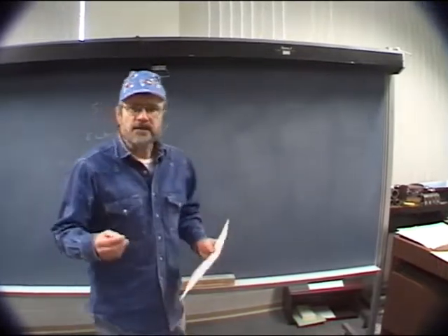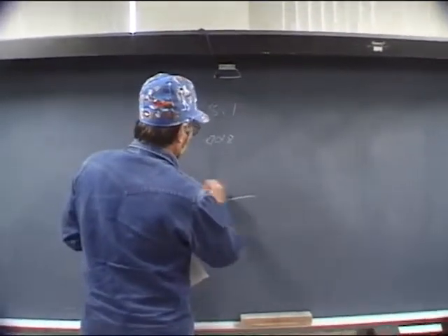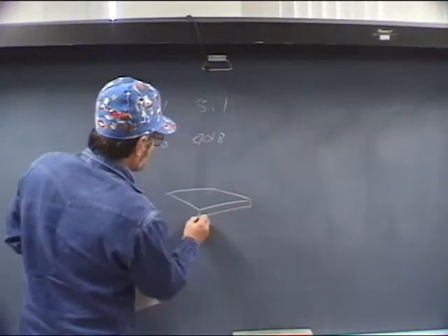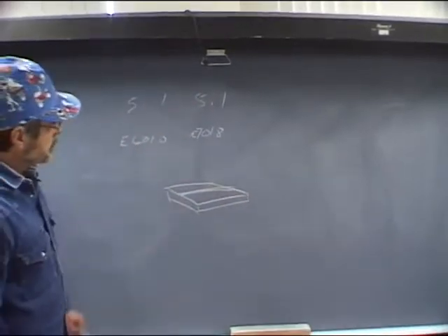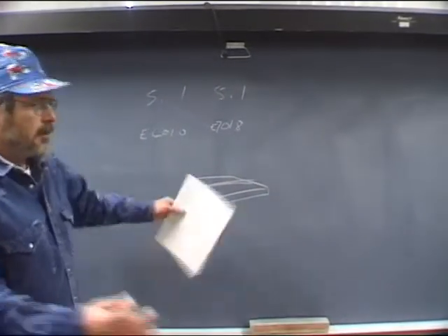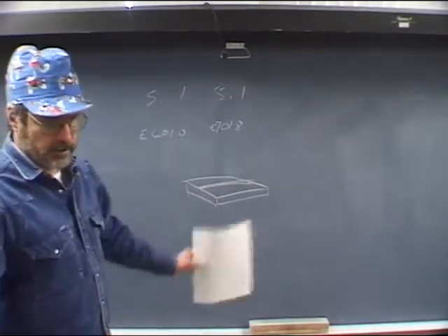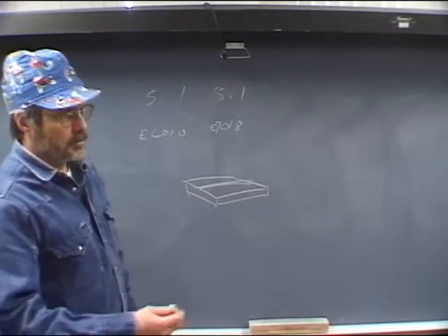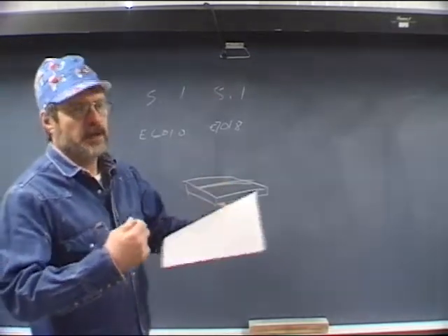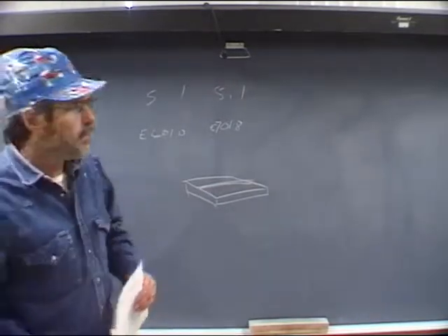And incidentally, under ASME, you can actually take some plate and lay it down on a tabletop and just weld it right there, do the necessary mechanical testing to it, and qualify a welding procedure. Some companies like to do that just to get the procedure qualification out of the way. A lot of other companies would do it the way, using the scenario we've been using, so that they can qualify the welder and the procedure at the same time.